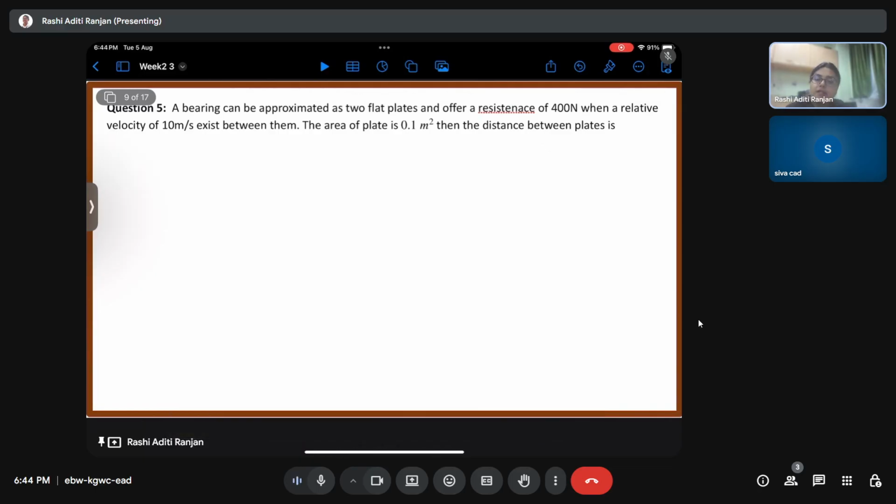So as we know, for viscous damping we had F equals Cx dot. This was applicable for the viscous damping part, right? Where we were actually considering a fluid, because of which, if a force was applied, there was parallel movement of the layers which caused some sort of dissipation, and that dissipation was the reason that there was resistance.